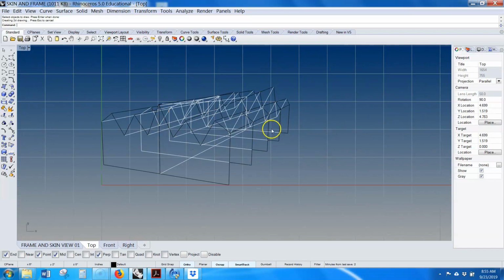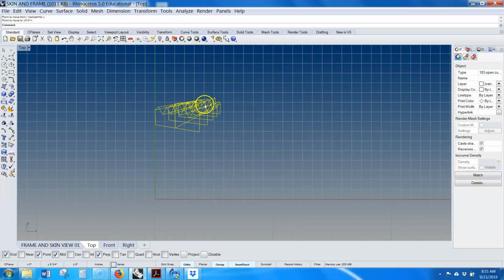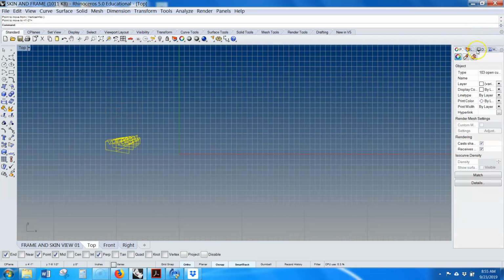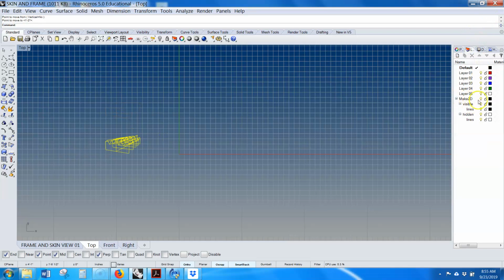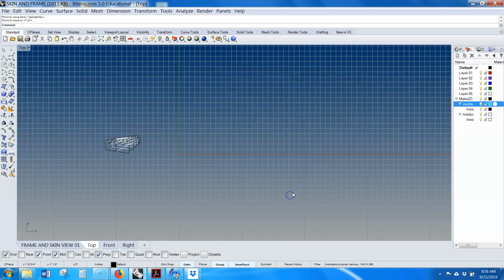All right, and you'll see that it's given me solid lines and white lines. So the black lines are solid, and if I look at the layers, it should say make 2D. Here are the visible lines. Watch, visible and hidden. So the hidden lines could be dashed. I like to change the color, like we would do it in AutoCAD.